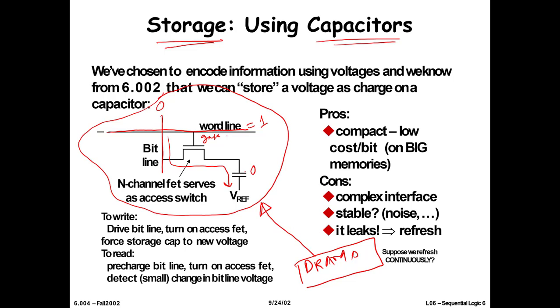to manufacture. So they take very less area. So that's why DRAMs can be manufactured with a huge density, and the cost per bit is very low, because you can easily manufacture the capacitors in large quantities. The downside is that it's leaky, so you need circuit to refresh it, and it has some nice problems, and